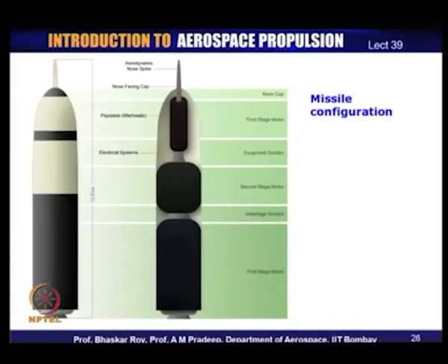This is a missile configuration. Now, this missile is basically finally is going to fly supersonic. So, if you look at the nose of the missile, you will find a supersonic spike over there, and that has been created essentially because some part of the missile flight is going to be indeed supersonic, and during which this nose over here will indeed create shocks, and the nose is then created to negotiate those shocks, create minimum drag and fly the missile efficiently through those supersonic flight conditions.